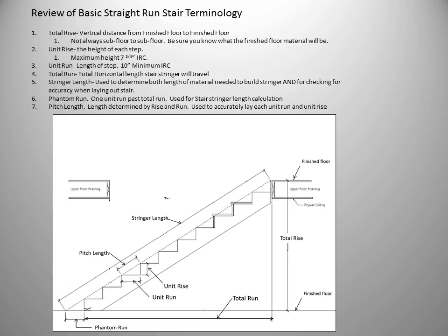To review our basic straight-run stair terminology, total rise is the vertical distance from finished floor to finished floor. Note that it is not always subfloor to subfloor. Be sure you know what the finished floor materials will be.